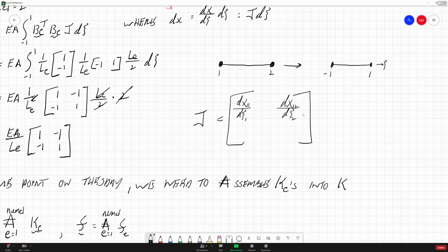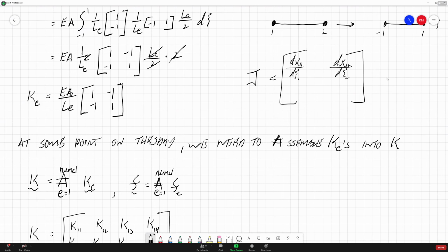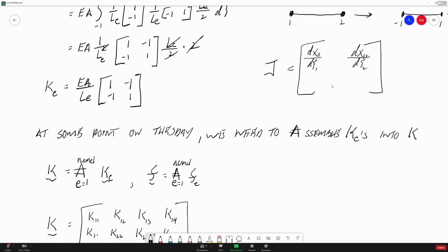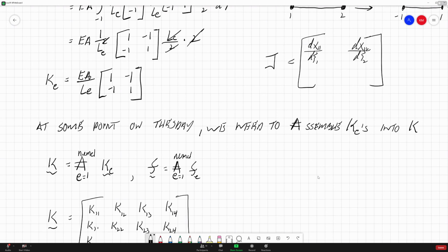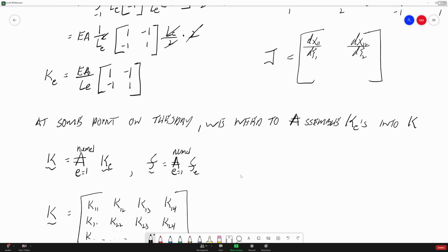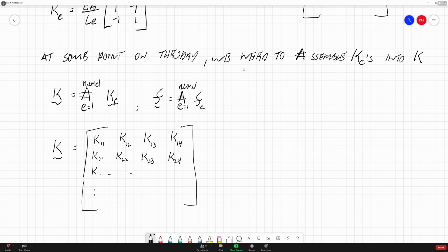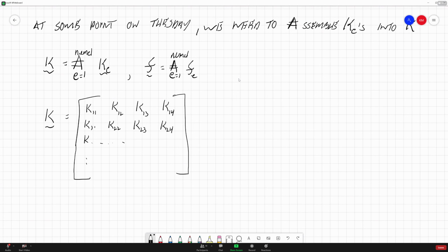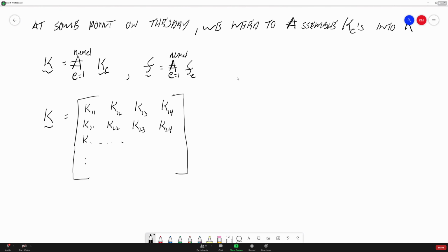So when you're doing a finite element solution and they say there's something going on with your Jacobian, they're just checks and balances that they found that, if that Jacobian doesn't look a certain way, you'll get an error flag and you have to check your solution. So something's not right. Maybe you have a boundary condition that's missing and you have a body that's moving.